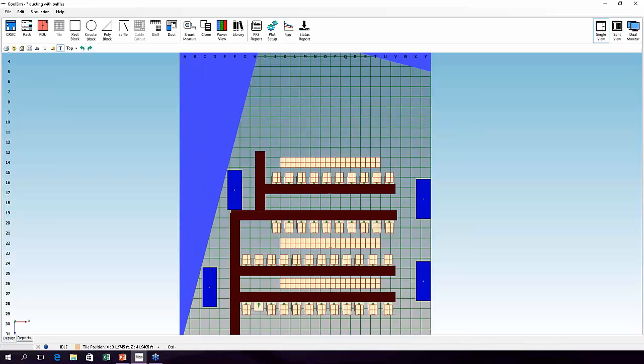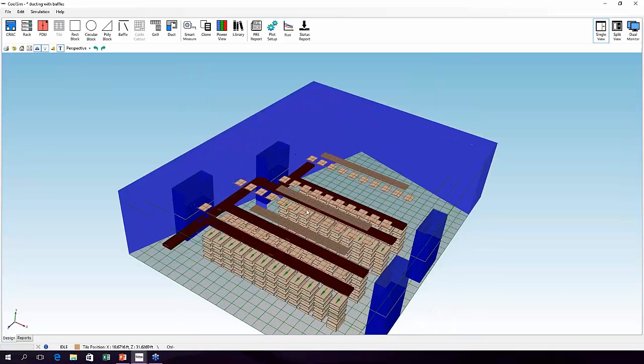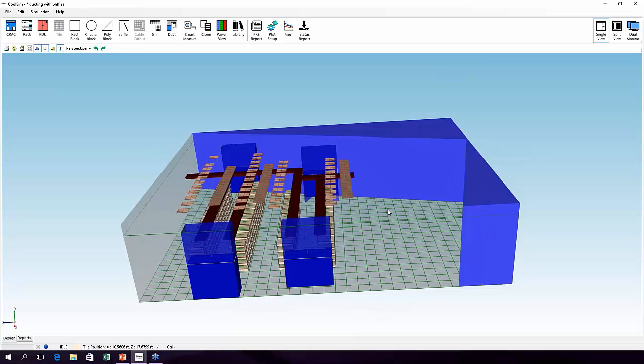If it fails in solve and your pressures you believe are okay, and again in this case I think they are because there's leakage that occurs, and let me show all again so we can see this model. But leakage is going to occur through that rack. In other words, pressure is going to be able to get up into that ceiling because it's not a sealed rack in the sense of airflow. So this one, if it fails, will probably fail because of a poor mesh quality. Quality means that the angle is incorrect, the skew is incorrect, or the aspect ratio, the shape of the cell is not correct. So sometimes that'll occur.